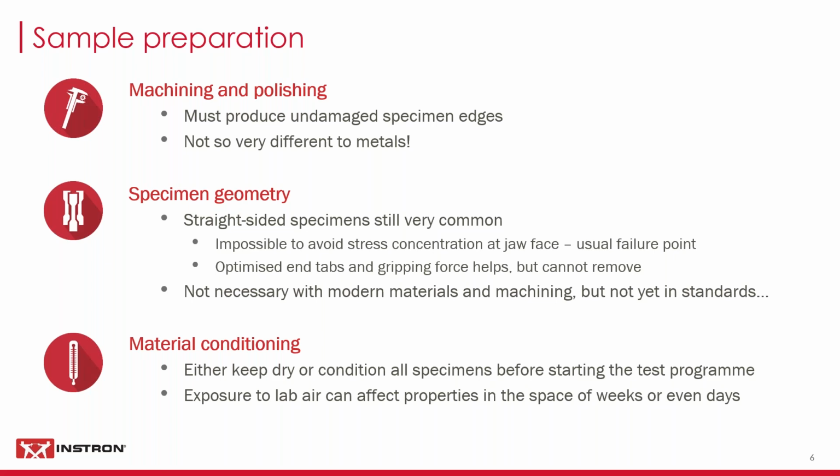Now, with a composite, that's not altogether true. Polymers, water diffuses through polymers. There's no two ways about it. And certain types of them, particularly the matrix materials such as epoxy resins, they absolutely love water. They love absorbing water, and it does unpleasant things to their mechanical properties. So it really does matter whether I make my plate of composite, slice it up and test it within two days, or if I let it sit for two weeks in the lab waiting for me. You will change the performance of the material, you will change your test results.